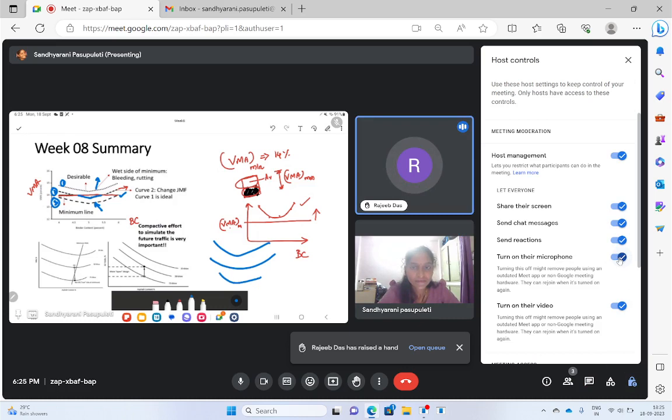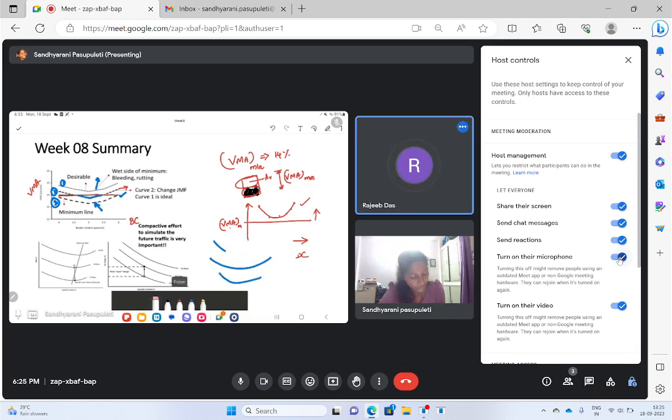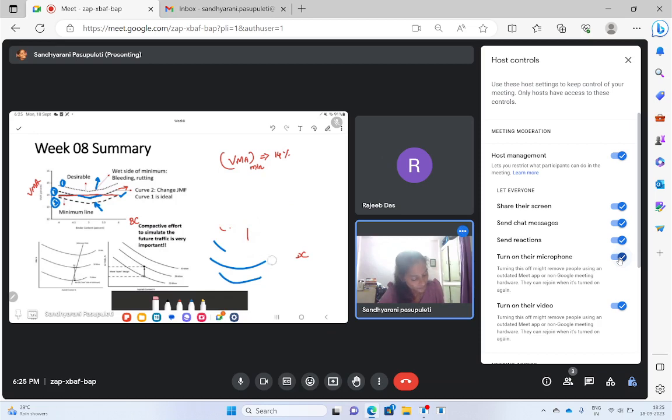Madam, why should the minimum VMA always be there? Why this diagram? I didn't get it actually. And what is this 14% you wrote? For example, if they have mentioned VMA minimum as 14, that can be 14, 12 or anything.